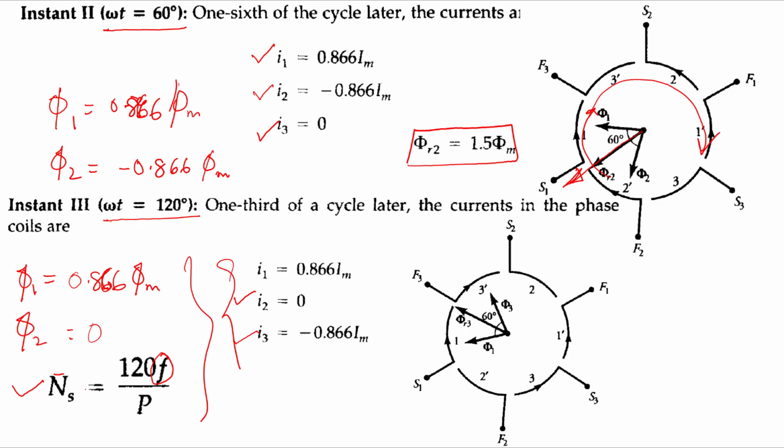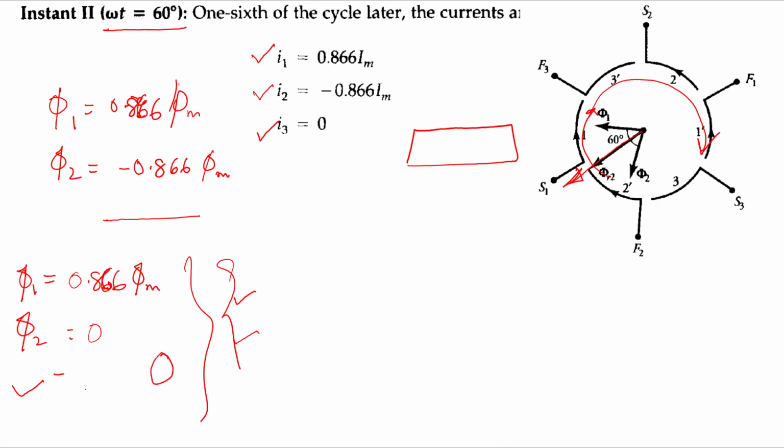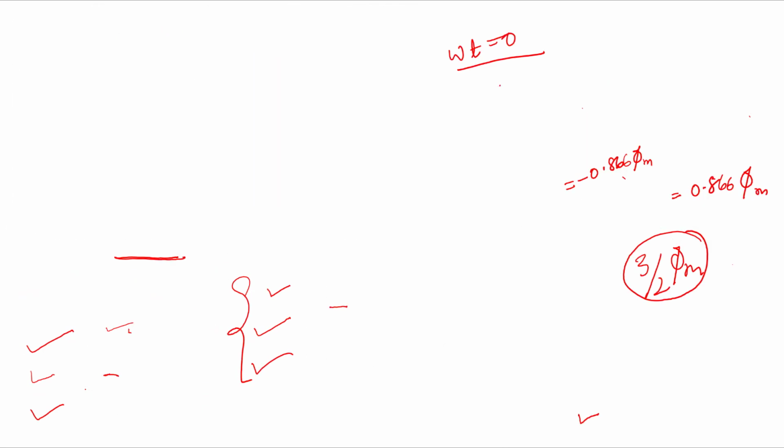So this flux is rotating at a synchronous speed in the stator, and we have another rotor circuit where the flux is unidirectional, and under starting condition it is zero speed, right? N is 0. So the rotor is not rotating. Now you gave a DC supply. So what will happen?